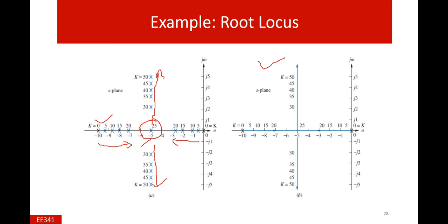This is the pole placement with the variation of K, and it shows that the root locus is actually the positions of the closed loop poles changing, starting at K equal to 0 and ending at K equal to infinity. But in our case, we are taking some limited values of K.